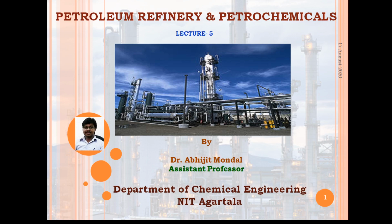That was unstabilized naphtha, which consists of LPG, light naphtha, and light gases. Then we had intermediate naphtha, for the temperature in between 135 degrees centigrade, and the heavy naphtha. Next, kerosene, light gas oil, heavy gas oil, reduced crude oil. So these are the products coming out from the atmospheric column. And